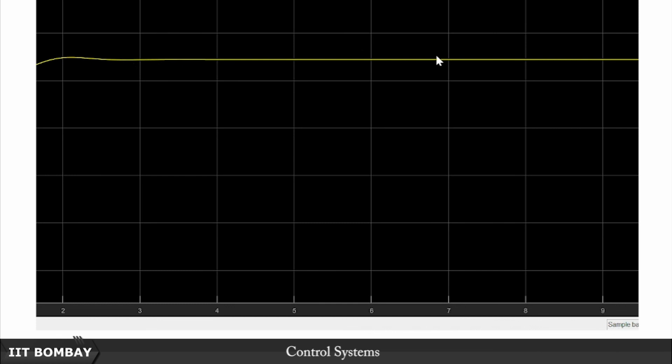So it means that my root locus based design is good, because remember there were so many factors there. We had to cancel out these pole and 0 pairs, otherwise we cannot approximate it like a second order system. But it turns out that for the design that I did, this pole 0 cancellation holds, and that is why this simulation is important.